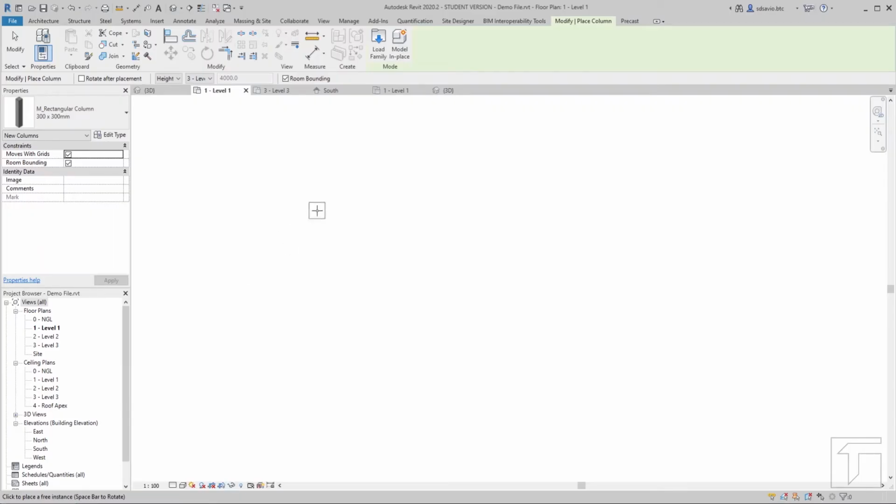So still on the column command, let me zoom out a bit by scrolling my mouse outward. My style here is first I rough in all the models. Unlike in AutoCAD, where you first draw all the lines that you need, then you trim them and cut them down so that you can make the shapes, here in Revit, since each of these components, like the column, belongs to a family, you can immediately draw them.